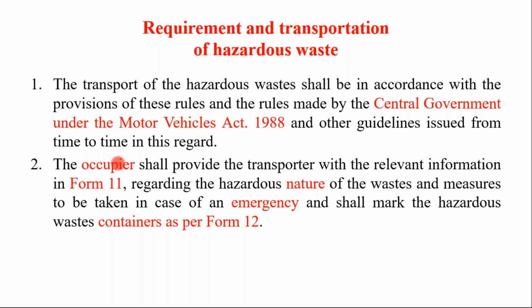So the occupier has to give the information to the transporter in terms of Form 11. This Form 11 is available in that Act, and it concerns the hazardous nature of this waste and the measures to be taken in case of emergency, and the occupier shall mark the hazardous waste containers as per Form 12.